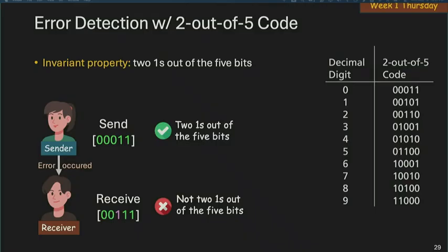Right. And then the minimum Hamming distance is a way to measure in general how many bits of errors are needed to confuse me, so that these errors will mask out with each other to appear as another valid code word. So in this case, if there's a 2-bit error in our communication, you might get, let's say, 00110.